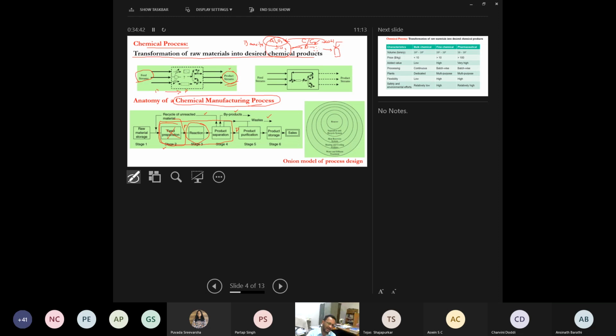So here you have the product. This product will have Al2O3, SiO2, sodium aluminate, sodium silicate. That is a very dangerous one because normally it is very sticky in nature. It's like gel type. So if the process conditions are altered, what will happen? It will clog the pipelines. Okay. So the very first step in the separation process is that we have to remove the sodium silicate.